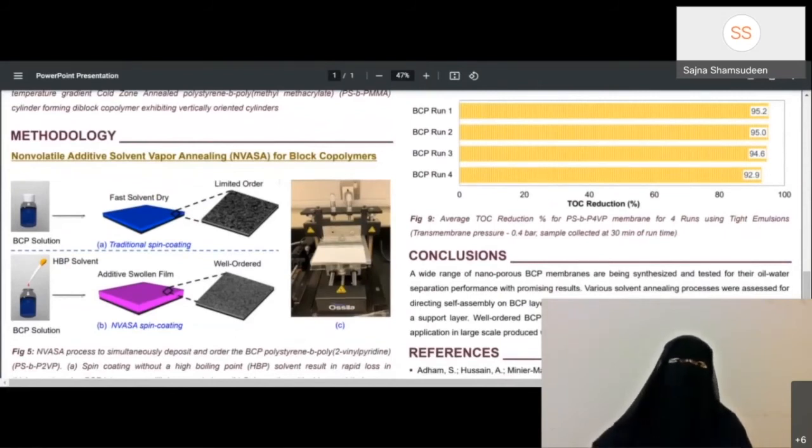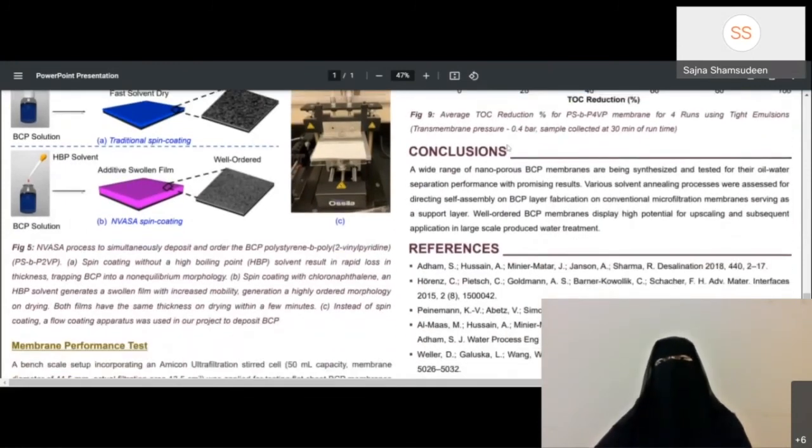The results emphasize the high selectivity of the membranes, high resistance to fouling over multiple runs, and their excellent oil separation efficiencies from wastewaters. In future, the membrane performance will also be evaluated for real field produced water samples procured from an oil and gas company in Qatar.